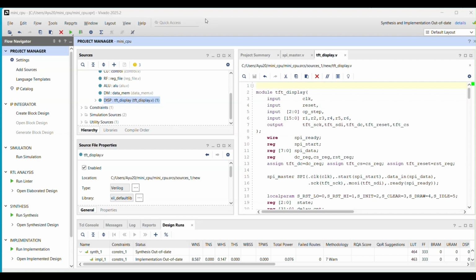Hardware reset via the RST pin, followed by software commands like SLPOUT to wake it up from sleep, COLMOD to set the RGB color format, and DISPON to turn it on. The entire screen is then cleared by writing 40960 bytes.